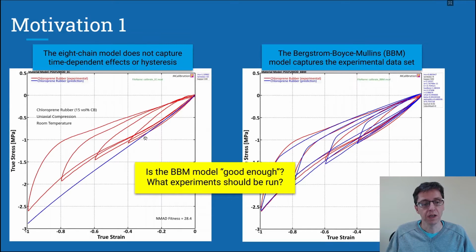And what do we see? Well, we'll see that the fit between the experimental data and the material model is not so good anymore. Say at 40% compression, the experimental curve here could be down at 0.75, but in the prediction from the hyperelastic model could be at least twice that. So 100% error in that prediction. Not so cool anymore, right? Clearly this is a problem.